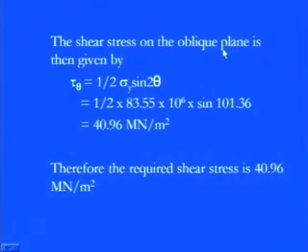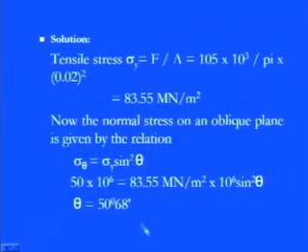Now we know the location. Once you know the location, you can easily get the value of the shear stress. If you move further, you will find the shear stress at this plane, where theta is 50.68 degrees. This theta is for the normal stress component. If you want to calculate the shear stress part, we simply need to put that particular theta in the relevant formula.